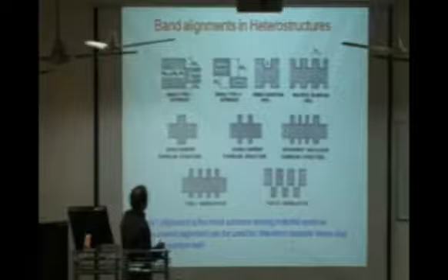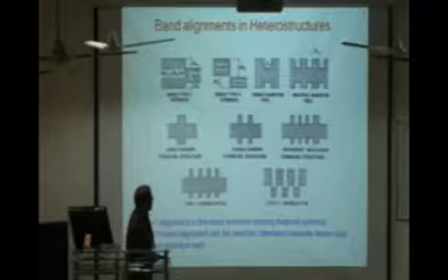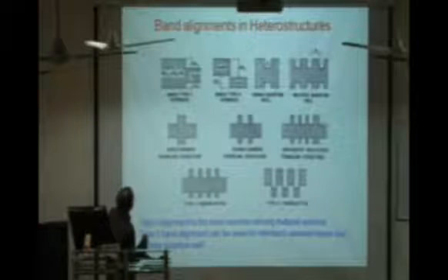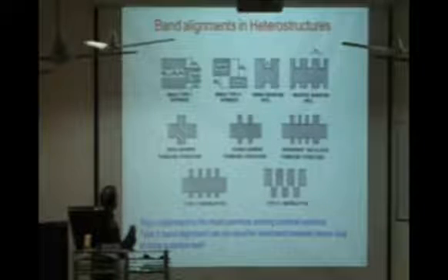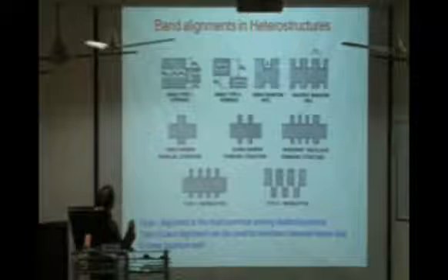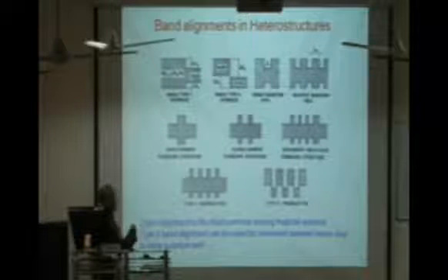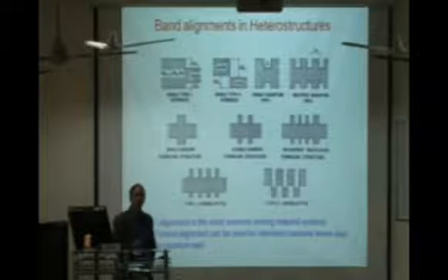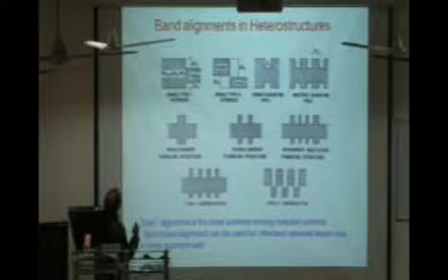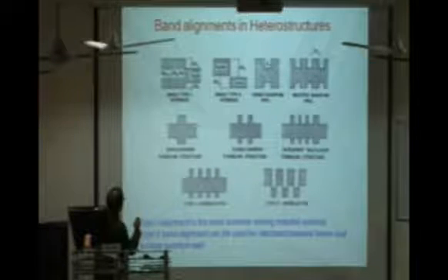Okay, so I'll come to this also. Till now we have seen that if you have one barrier, one high band gap semiconductor and a low band gap semiconductor, we make heterostructures. Heterostructures can be of different types. It can be type 1. In this example, I have taken gallium arsenide, a very common example, as the low band gap semiconductor, and gallium aluminum arsenide of a particular composition as the high band gap semiconductor. They have been chosen because they have the same lattice constant, so one can be grown on another without any defects experimentally. And as you see, we have a conduction band offset and a valence band offset. So our quantum energy states have to be confined within these offsets.